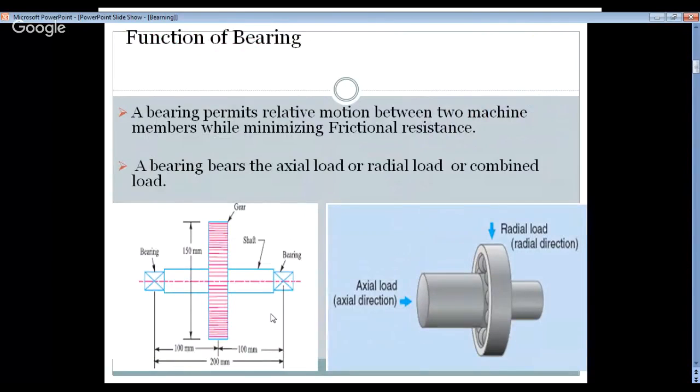if the bearing is mounted here, when the system is not running, the rolling element which is exactly below all the other elements is heavily stressed, as the weight of the shaft, the radial load of the shaft, is acting continuously.